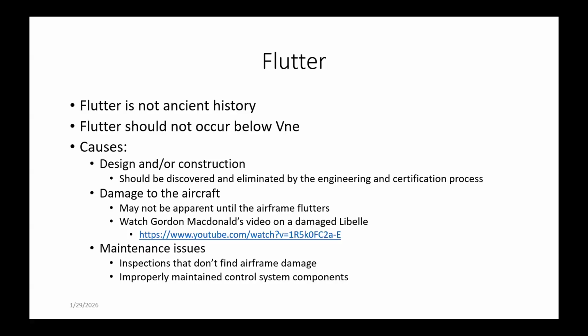I had a case of flutter on my first fiberglass glider. The rudder was unbalanced. Now, in defense of the previous owners of the glider and the designer of the glider, at the time that plane was built back in the early to mid 70s, anything that had a red line below 120 knots, they didn't believe needed to have balanced controls. And it turned out that my rudder had been refinished and it was even more unbalanced than it had been when it came out of the factory.